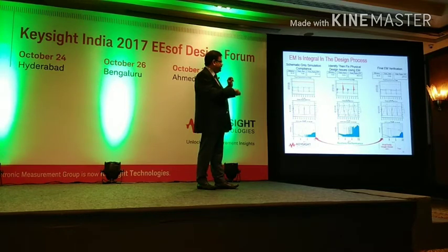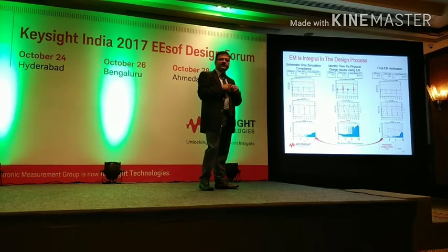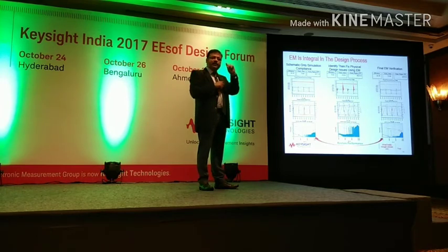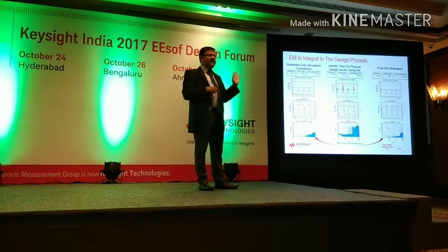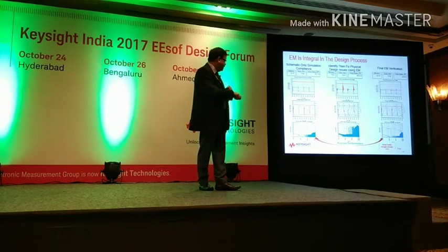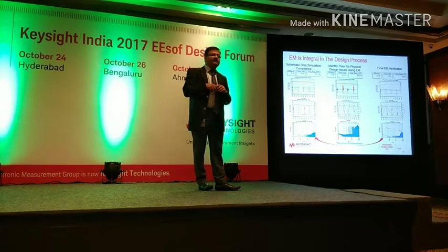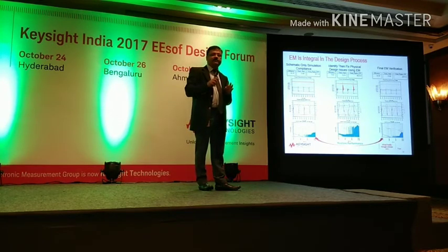When you went ahead and did the simulation with first cut layout, you can see the spikes are even crossing the breakdown voltage limit, which was 30 volts. Yeah? So your output is only 5 volts, and with spikes you are crossing the 30 volt limit. So dangerous. Gate drive looks a little messed up, a lot of spikes and overshoot. And if you look at spurious, it's all over the place beyond a certain frequency. I think it's beyond 2 megahertz onwards. Everything is above the limit line which you are supposed to comply to.